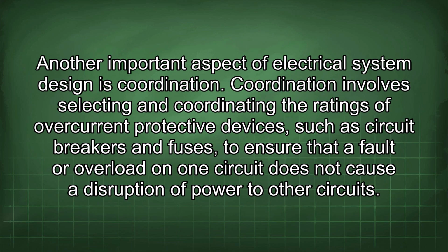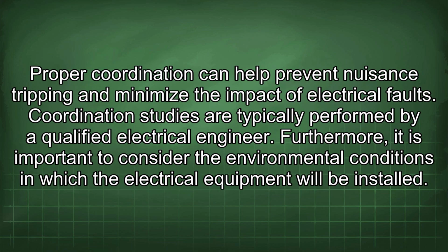Another important aspect of electrical system design is coordination. Coordination involves selecting and coordinating the ratings of overcurrent protective devices, such as circuit breakers and fuses, to ensure that a fault or overload on one circuit does not cause a disruption of power to other circuits. Proper coordination can help prevent nuisance tripping and minimize the impact of electrical faults. Coordination studies are typically performed by a qualified electrical engineer.